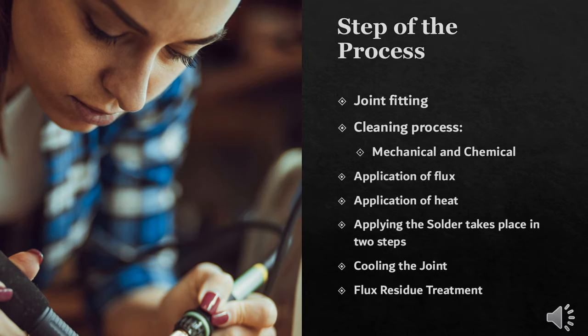In this process, as soon as possible after the soldering process, the material should be cooled using water spray or maybe an air blast or maybe another liquid that can speed up the cooling process. After that, we go to the next process, which is flux residue treatment.